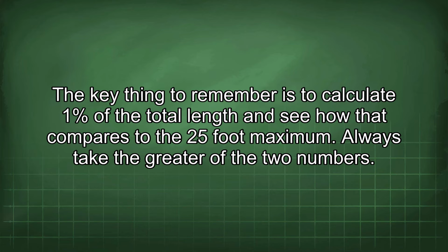The key thing to remember is to calculate 1% of the total length and see how that compares to the 25-foot maximum. Always take the greater of the two numbers.